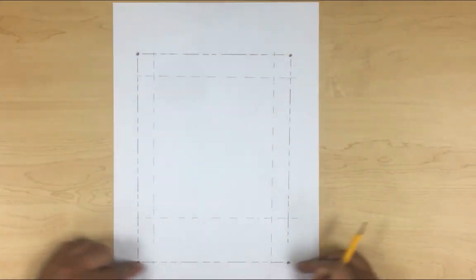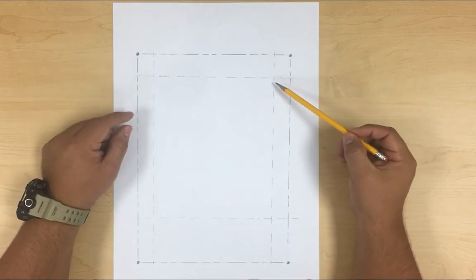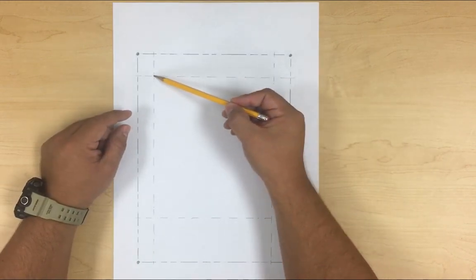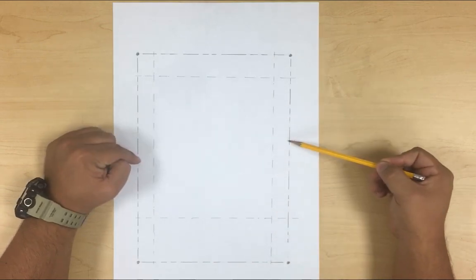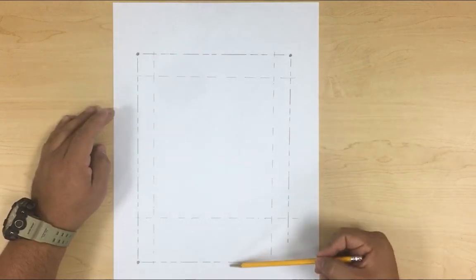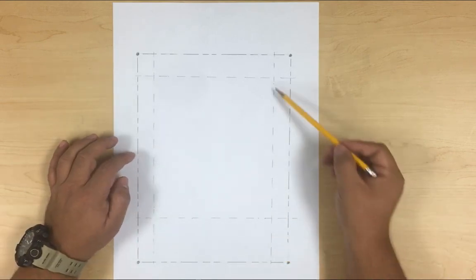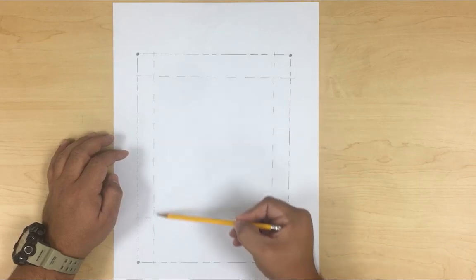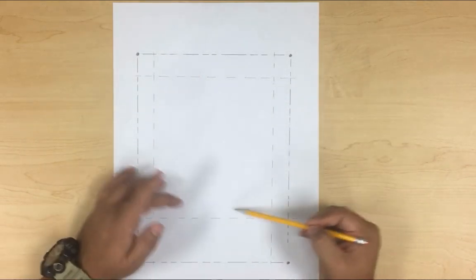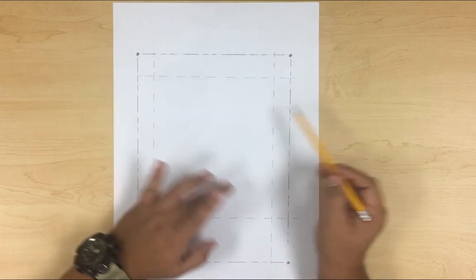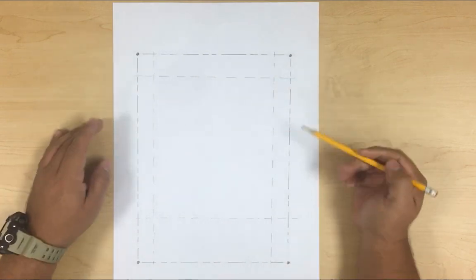We have defined where the property is, and we have defined where the setbacks are. That means we can build our house anywhere in this area right here. We need to respect the 7 feet, the 10 feet, and the 20 feet. Again, these are going to vary. Inside here, you can put the house wherever you want, according to your design. You want it in the back, put it in the back; in the front, or on the side, it doesn't matter, as long as it's inside here and you respect your setbacks.